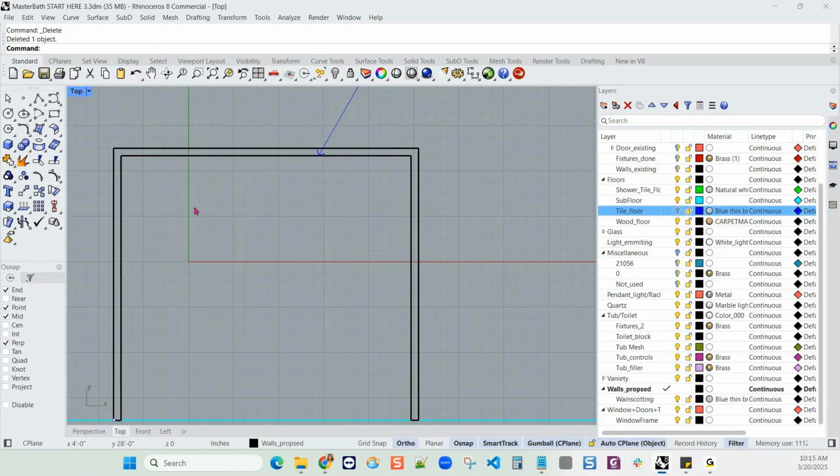Okay, but let's roll back. What if Smart Track just isn't working for you right now? You can create the rectangle at the corner. And the same way we did, it's 4 by 4'8". And again, we need the -4'8". So it moves down in the Y construction plane.